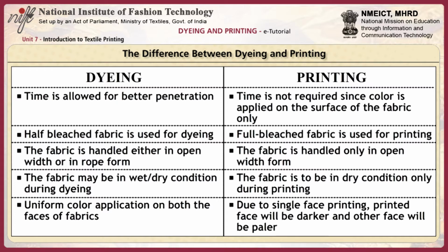During dyeing, the fabric may be wet or dry, but during printing, the fabric is to be kept in dry condition. During printing, color is applied on one face of the fabric, but due to single-sided printing, the printed face will be darker and the other face will be paler.